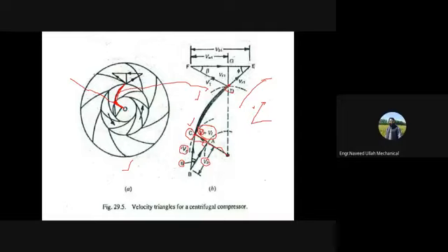In hydraulic turbines, there are wicket gates. Those wicket gates are nothing but the guide vanes, and they are fixed. You can change the direction, but you need to stop the process and then change it, just like changing the pitch of the propeller in a propeller type aircraft. So you can have then pre-whirl,